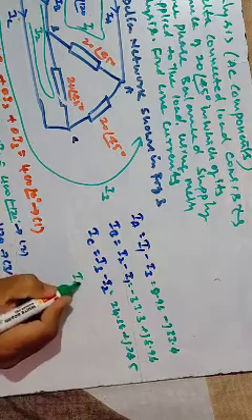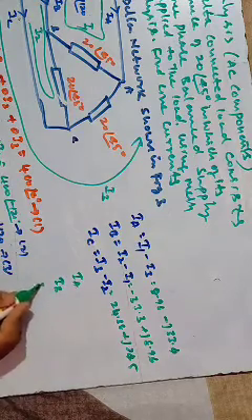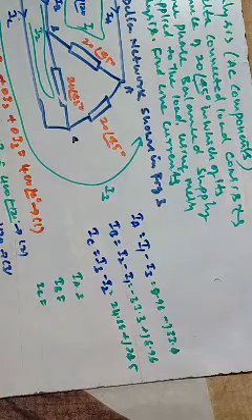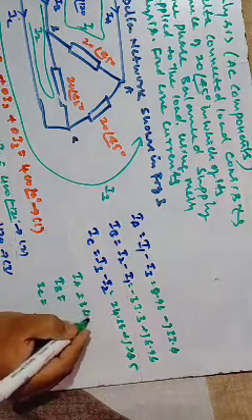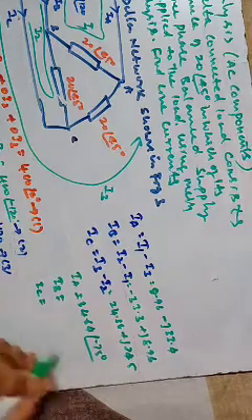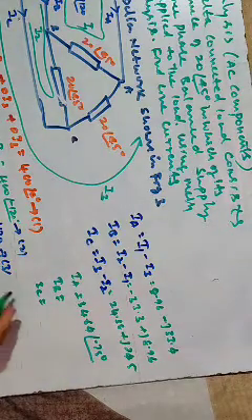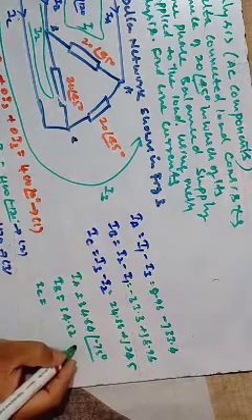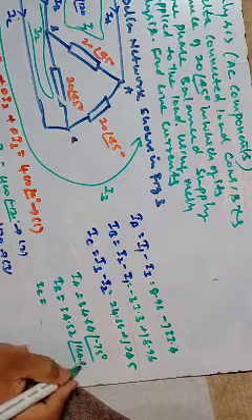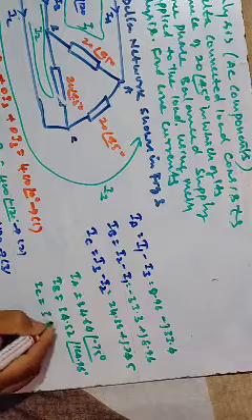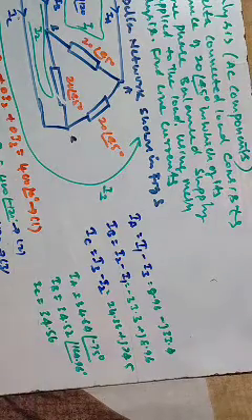We may also write them in polar form as IA, IB, IC. Converting that rectangular form into polar form, our answer is IA equal to 34.64 at an angle of minus 75 degrees, IB is 34.52 at an angle of 164.96 degrees, and IC is 34.56 and the angle is 45 degrees.